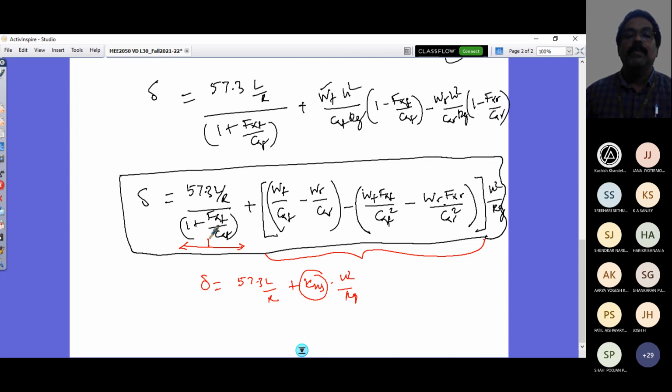So this is term 1, because this has now been altered. The Ackermann steering angle is now changed because of the drive force acting on the wheels. So it is divided by this factor that I have to consider. And this term is term 2, this good old understeer gradient considered from the tire compliance alone.